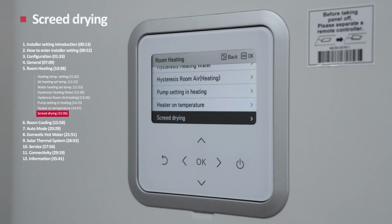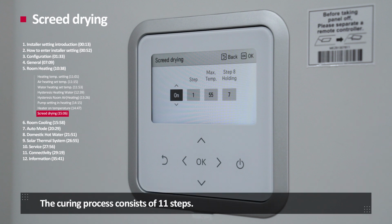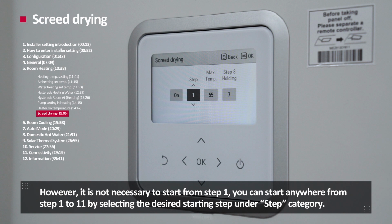Screed drying. Screed dry setting is to help with curing the new cement floor after construction by using floor heating for a certain period of time. The curing process consists of 11 steps. However, it is not necessary to start from step 1.